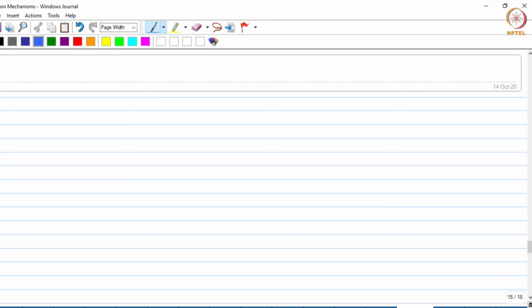Right? So if you have lost these particles due to this dissolution process, then your grain refinement ability is also lost, okay? When the particles themselves are not there, how can you expect them to act as grain refiners? So this is one theory of fading, which says that the particles would ultimately dissolve because the solubility of titanium in liquid aluminium is much higher compared to the concentration in which titanium is actually added, okay?